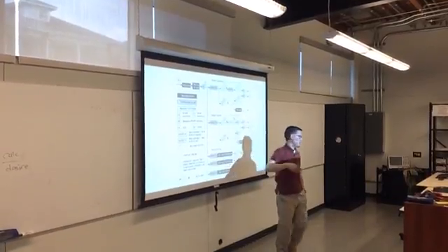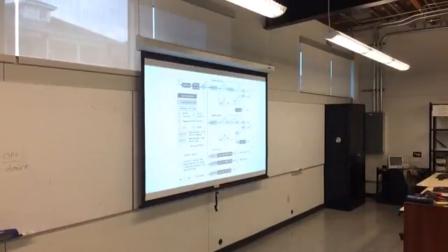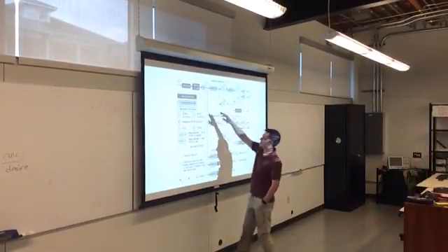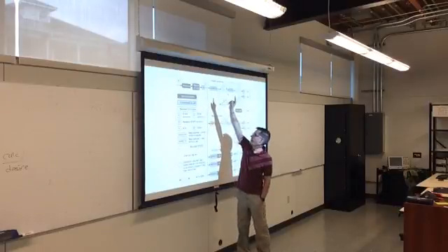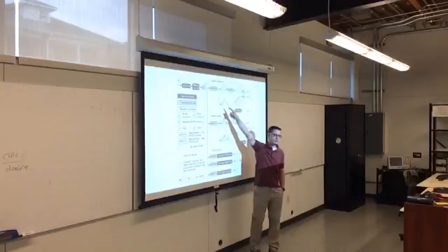If you don't stop the bus, that means you never release the bus, and when you come back to that code, you'll be in the wrong state. So you don't want to write your code and just go, let me transmit this. Ah, crap, I got nacked. And then you just type return. You can't just bump out of your code. You need to complete this machine and either do a repeated start or a stop. You have to follow this machine through.